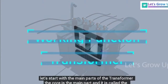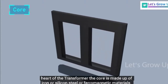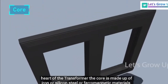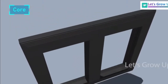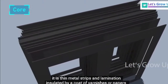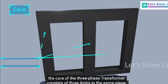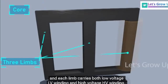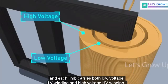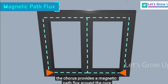Let's start with the main parts of the transformer. The core is the main part, and it is called the heart of the transformer. The core is made up of iron, or silicon steel, or ferromagnetic materials. It is thin metal strips and laminations insulated by a coat of varnish or paper. The core of the three-phase transformer consists of three limbs in the same plane, and each limb carries both low voltage, LV, winding, and high voltage, HV, winding. The core provides a magnetic path for flux around the core.